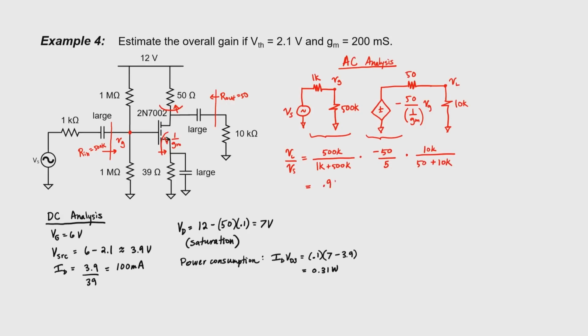This works out to 0.998, and that's really typical of MOSFET circuits. You hardly have any problem over at the input side because we're allowed to use large resistors there to bias the gate. Our gain segment is only 10 here, so it's more modest compared to what we would expect with a bipolar transistor in a similar configuration. Finally, we have an output voltage divider here, which in this example is 0.995. So basically, our gain is about negative 9.9.